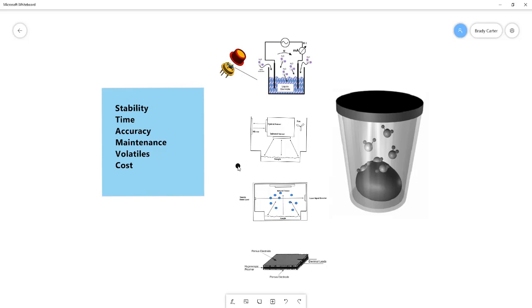And so to be able to make sure that they're meeting those specifications, you have to actually do some verification, and that comes to maintenance. And how frequently does that verification need to be done? For instance, on the dew point sensor, it will give very accurate results, but you do have to make sure that nothing's happened to affect that. And thinking back to the stability, again, if there's any kind of contamination on the mirror or the sensor, it will affect the readings. And so in order to achieve the high level of accuracy, you have to verify it and you have to clean it very frequently.